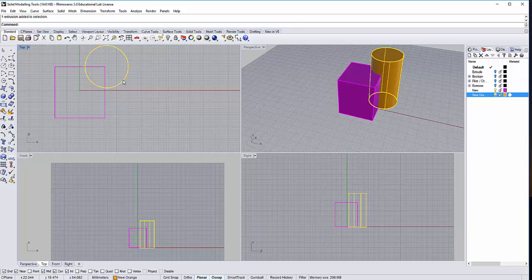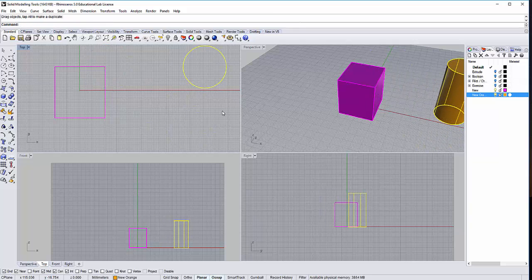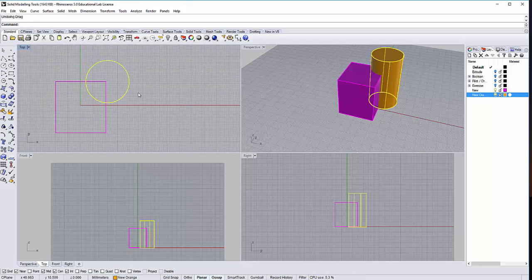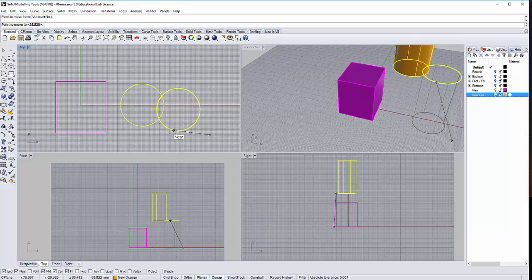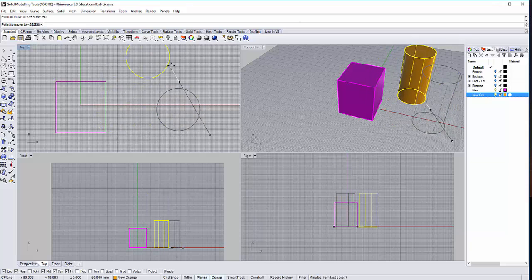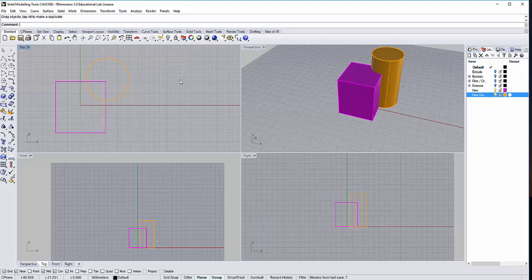Okay, we go through move by dragging. We go through move by clicking M. Where do we want to move? Let's say I want to move 50. I can move it like that. Okay, gumball condenses moving, scaling into one. To have gumball, you must switch on gumball.